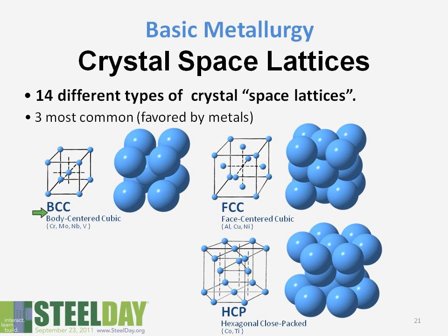Body-centered cubic refers to the unit cell having this cubic structure in 3 dimensions, plus an additional atom in the center of the body. Face-centered cubic means, again, we have this cube, atoms at each apex of the cube, but we also have atoms centered in each face of that cube. These are the 2 structures that we're primarily going to talk about.